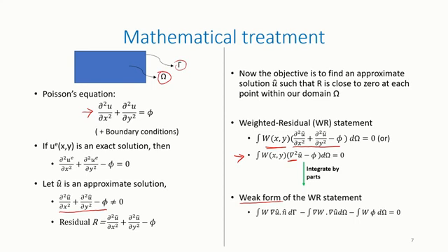And there is a reason it is known as the weak form, and I would like you to explore that aspect. If you observe the weak form equation, we have this term in terms of d gamma, which is a boundary term and is related to our boundary conditions. This weak form is one of the significant steps in the FEM process, and I would say this is where FEM starts.